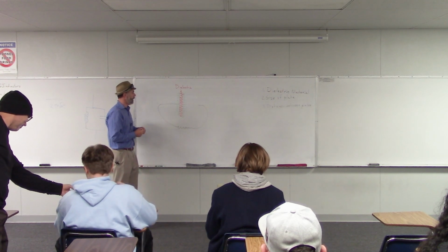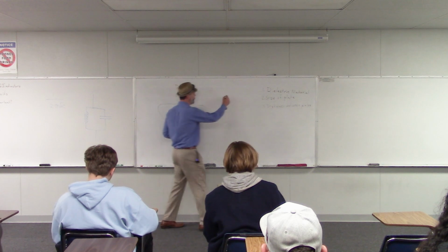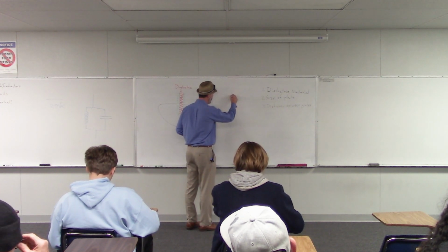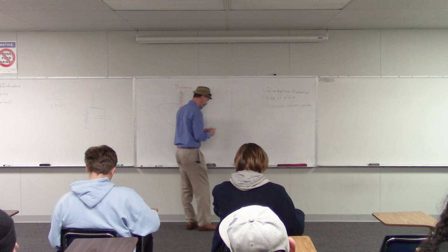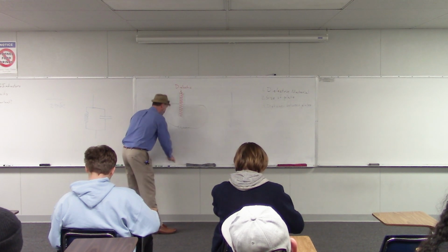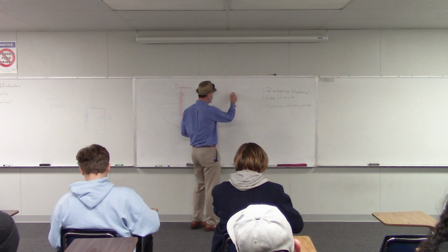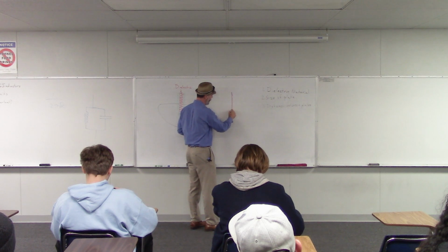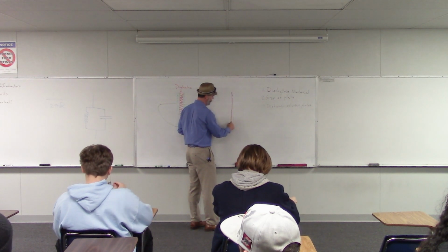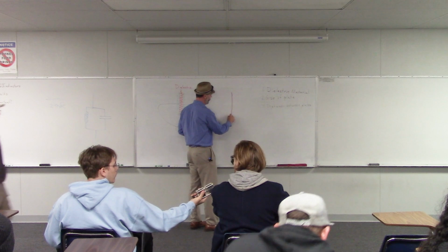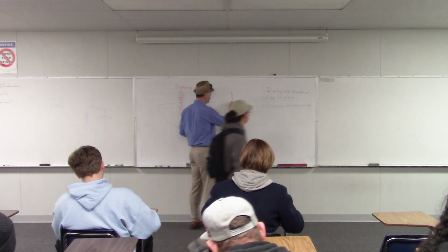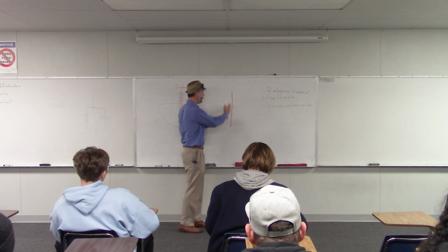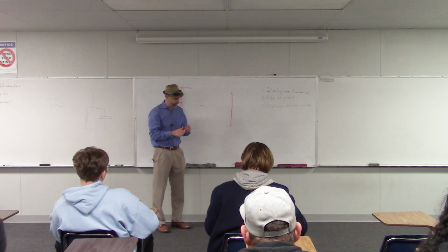So with electrolytic capacitors, they start with this piece of foil and then oxidize one side of that foil. They put it through a chemical process where you end up with a very thin layer of oxidation, almost like rust, but it's the equivalent for aluminum. Anyway, it's oxide, it's non-conductive, and that becomes your insulator on the one side of your capacitor.